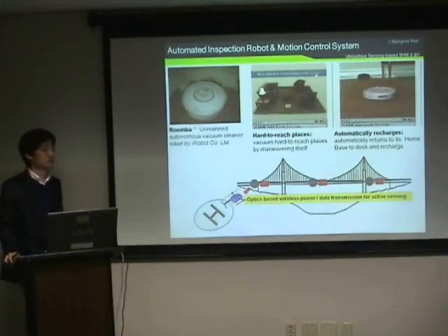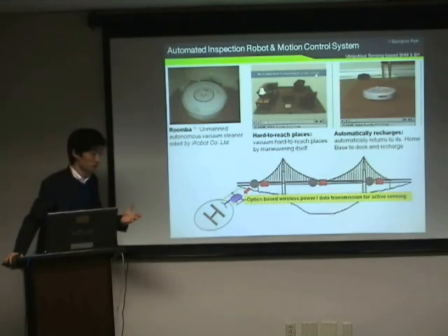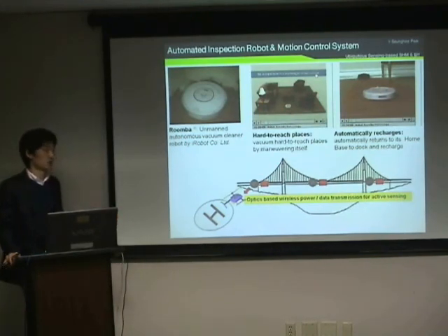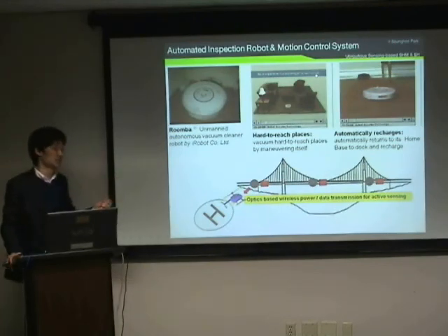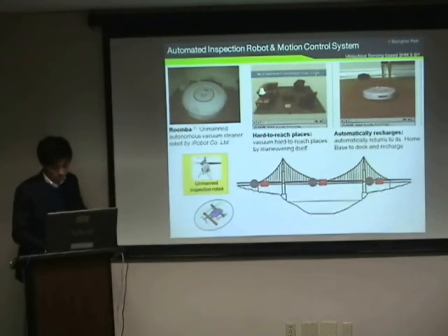How did you do temperature control? Because I noticed in some of the slides you said that some of the data was corrected for temperature. How did you do that? When you're doing identification, were you controlling for variability in the temperature, like stiffness changes due to temperature? Did you correct for that? That's why we need to employ a temperature compensation technique, right? What technique did you use?